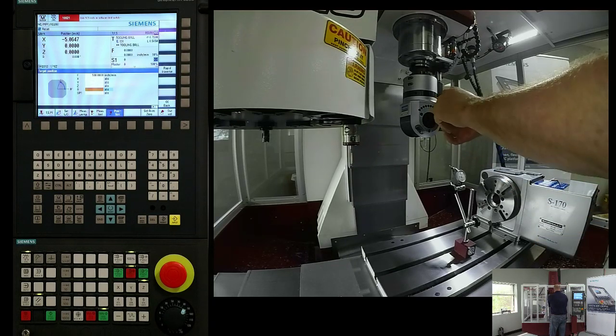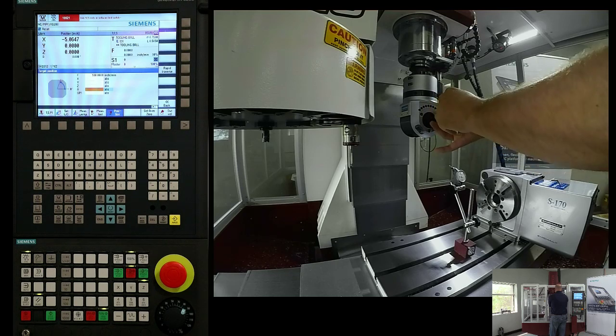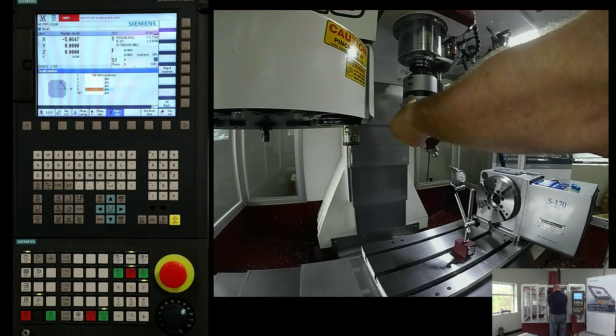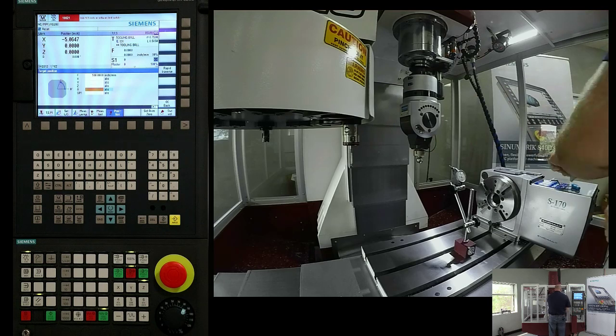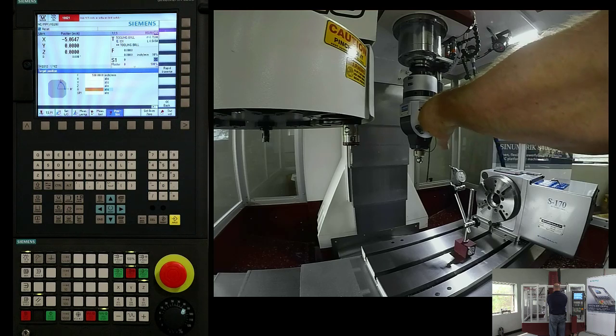One of the things that's extremely common in these kinds of heads, and is to be expected, is that as I rotate the C-axis, it's not rotating concentric to the Z-axis or my spindle. It's actually going to run out. Because of that, as I induce any rotational moves in my C, it would affect that tooling ball check. It would not continue to be accurate the way it is as I move my C around.